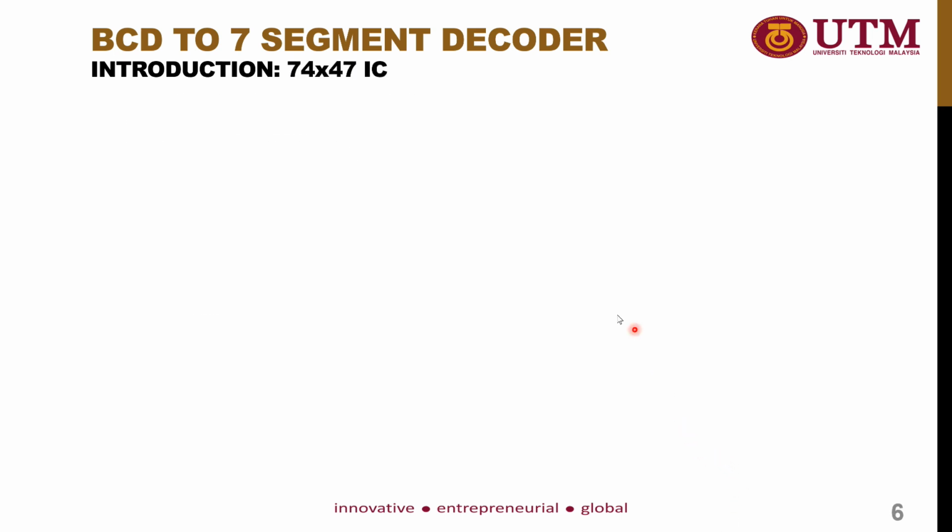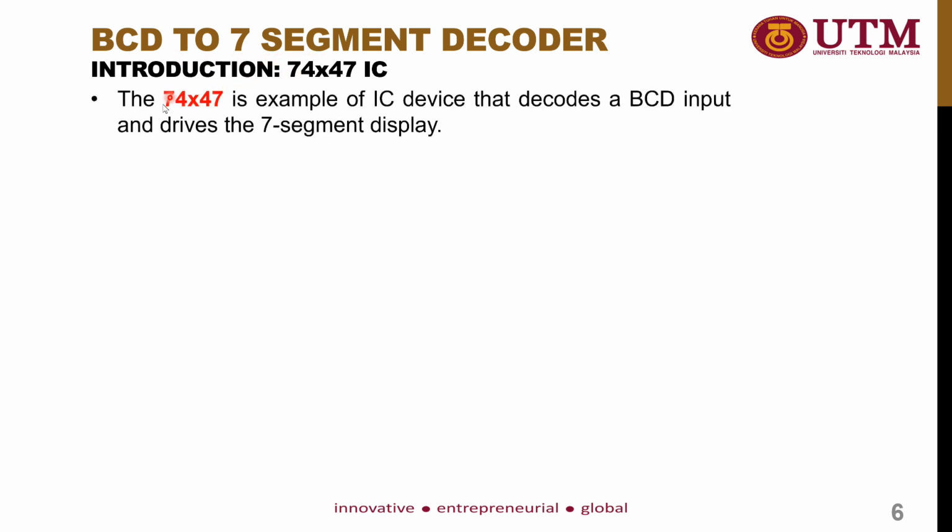Next, we go through the 74X47 IC, which is a BCD to 7 segment decoder. The 74X47 is an example of an IC device that decodes a BCD input and drives the 7 segment display. We give the BCD input and it will decode the input and use it to drive the 7 segment display.